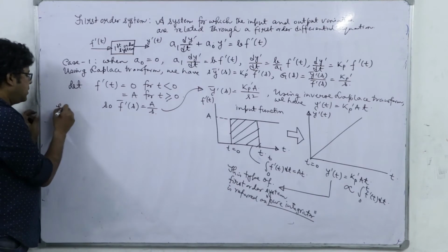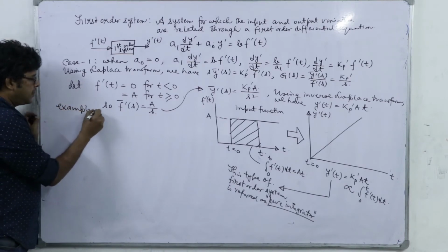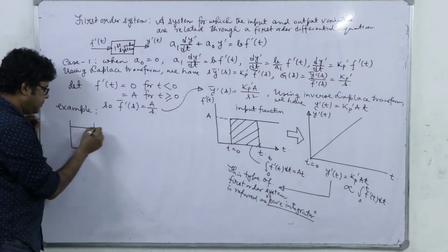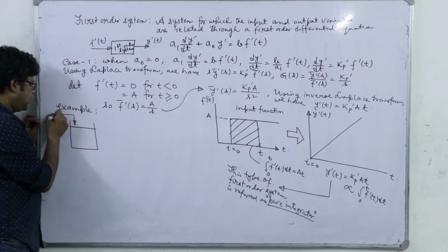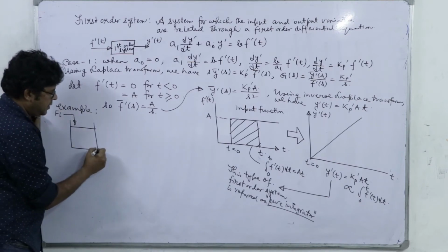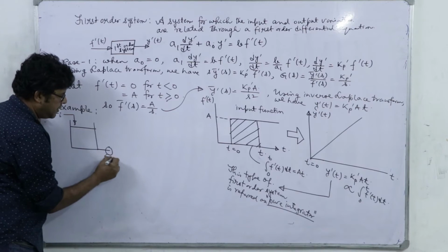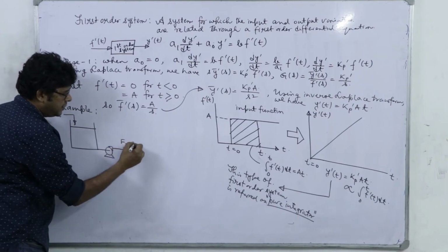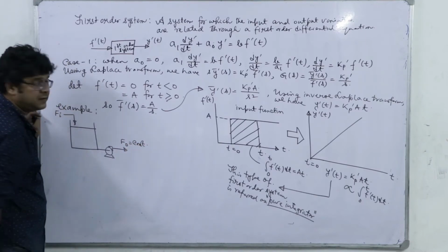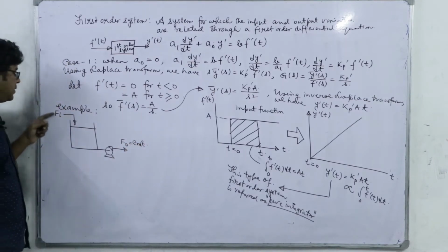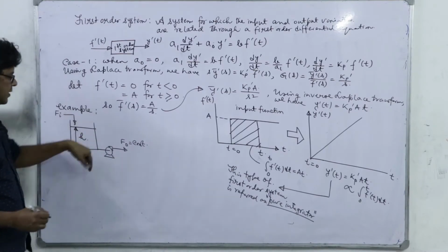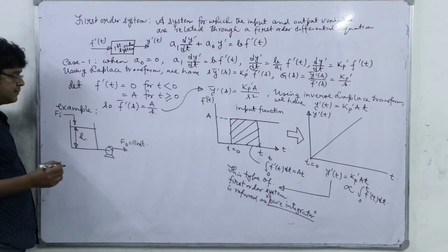Now example, you see we have a tank, input Fi, right, and here instead of a valve we have a pump where the outflow rate is F naught, and that's constant. It's invariant with time. It's independent of how this Fi changes, because there is no manual or controller intervention, unlike a valve.